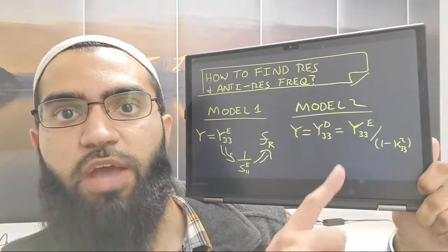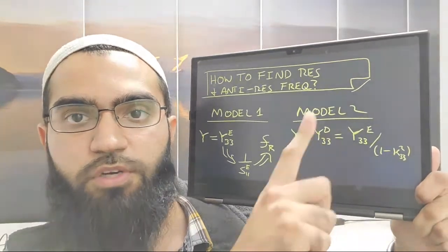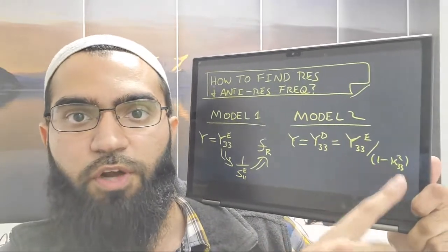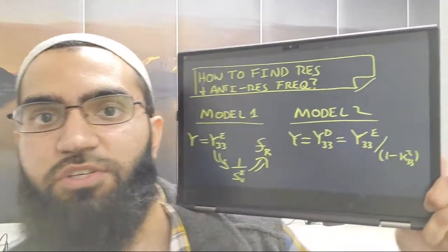So you can convert that into constant electric displacement from constant electric field through the coupling factor, and those are usually given on the data sheet. So that can be an easy calculation to do. Now, the caveat here is there's assumptions, like there always is in life. So the assumption here is the stress or strain in the piezo is relatively constant. That would allow you to do this method. If you have a lot of variation of stress in your piezo, it's not going to work.